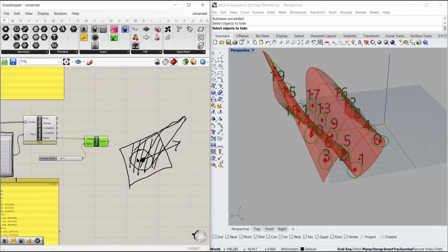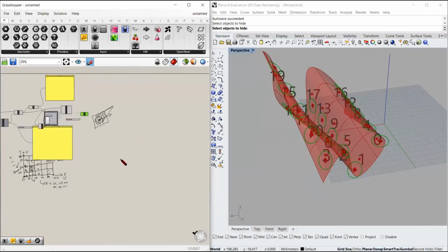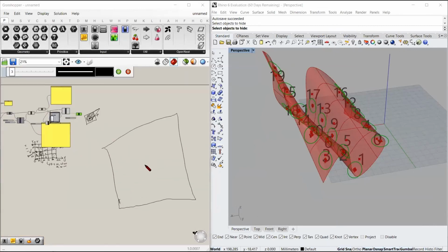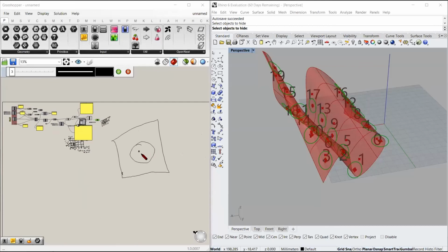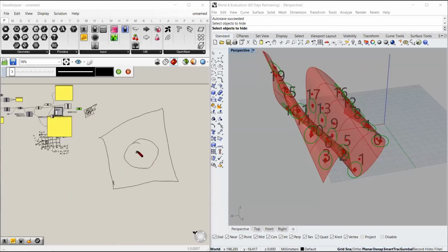For that, firstly, we had a surface, we evaluated a specific point, we made a circle on that specific point, and now this final step is to move this point in a perpendicular direction and use this circle and this point to make a conical expression. So we already did these steps. The fourth step is to move this point, and the last step is to extrude this circle to that point.